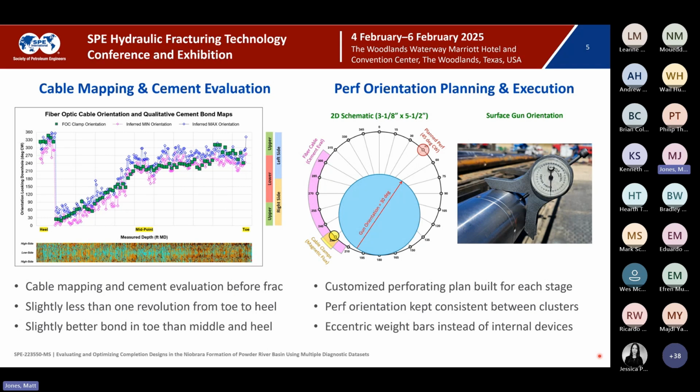So every perf for a stage is shot at the same orientation. Also, no phasing between perforations, meaning they're all shot in a line. And as I said, eccentric weight bars instead of internal devices.